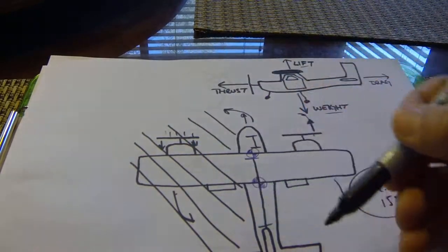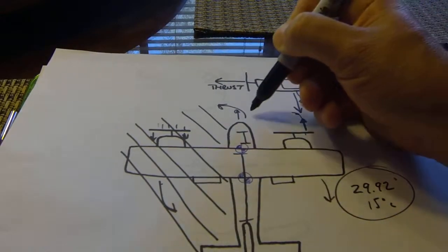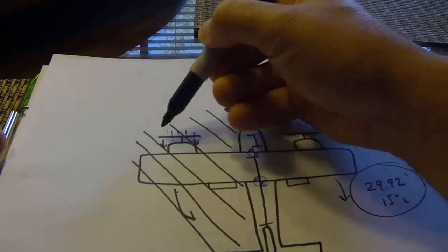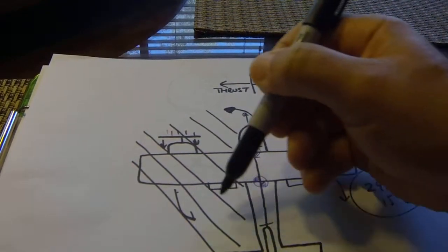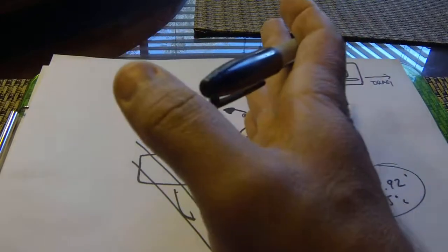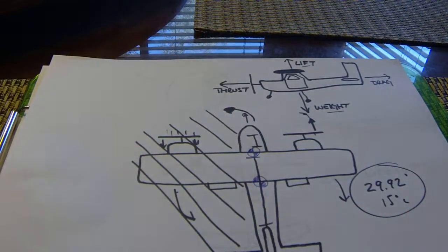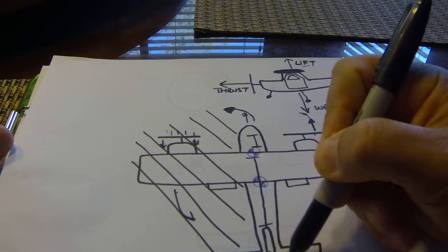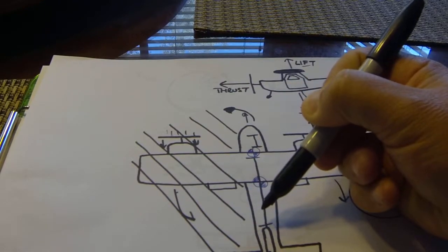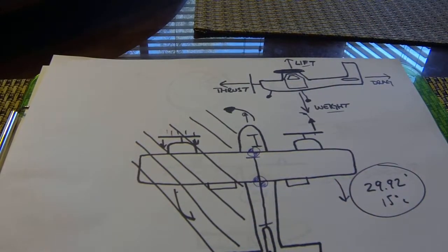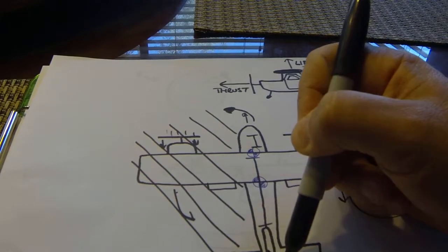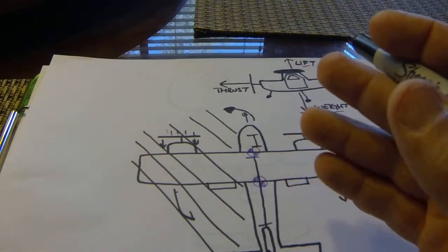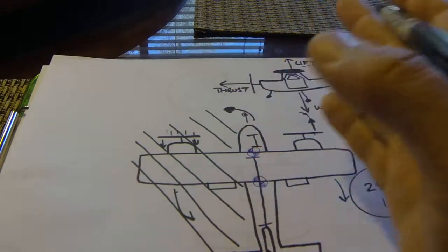Furthermore, this side slip further exacerbates our left turning tendency. Why? Well, it's pretty obvious. The air is pushing on this side of the aircraft. It's pushing on the vertical stabilizer, and we're trying to rotate about the center of gravity. It also decreases the effectiveness of the rudder. So we've got this rudder over here. It's decreasing the angle of attack for the vertical stabilizer, masking the rudder in some way, shape, or form, and we're losing the ability for directional control.